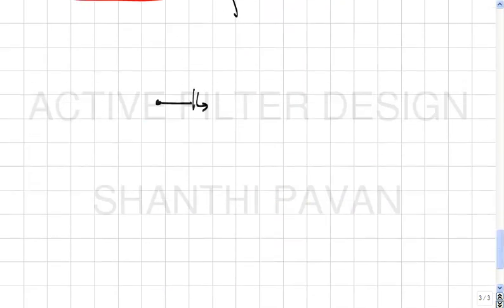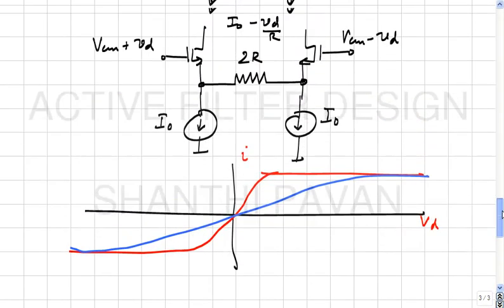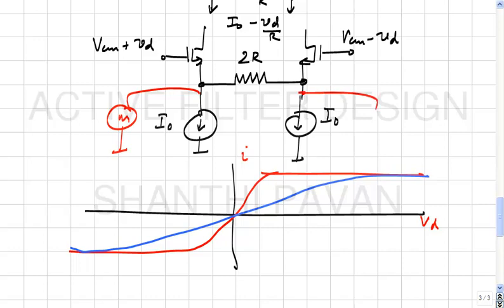So as far as noise is concerned, earlier the noise of that 2 I0 current source would split equally among the 2 halves and therefore would not appear in the differential mode equivalent. Now what happens? The noise current of this current source and the noise current of this current source are completely uncorrelated, correct? Because they are happening in separate devices. Okay. So can we now say that this noise can be rejected, can be neglected because of differential operation?